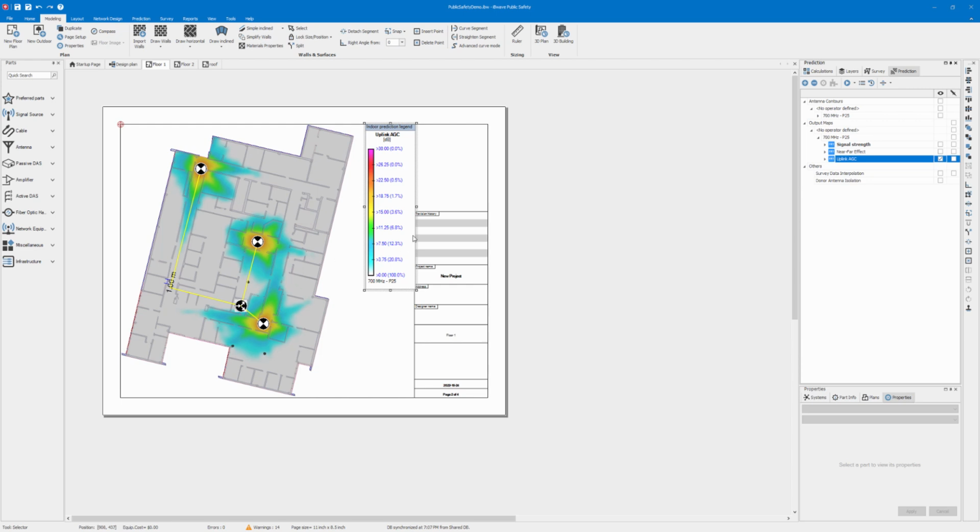So the legend by default is set to this color. Basically white transparent is anything 0 or below, simply meaning no AGC was required to be applied to lower the output power. And the colors from cold to warm mean a higher value of AGC has been applied. Even using the tooltip could be useful to see where your network gets attenuated the most. This sums it up for the Uplink AGC map as well.